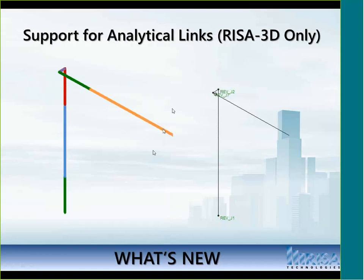We've added support for analytical links, and so those analytical links in Revit will now come into RISA 3D as rigid links. And similarly, if you draw a rigid link in RISA 3D, it'll now come over into Revit as analytical links. So this helps a lot with the column beam offsets and the such.